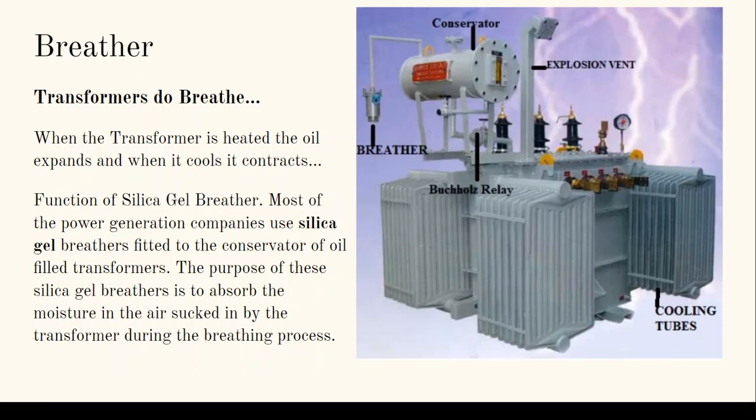When I say breathe, during the day you have high loads for the transformer, where the transformer oil inside the transformer heats up and expands on heating. When it expands on heating, the oil inside the transformer through a tube goes through the Buchholz relay and goes into the conservator. So the oil rises inside the conservator. When the oil rises inside the conservator, the little air gap or the air pocket inside the conservator vents out the gas through the breather into the atmosphere.